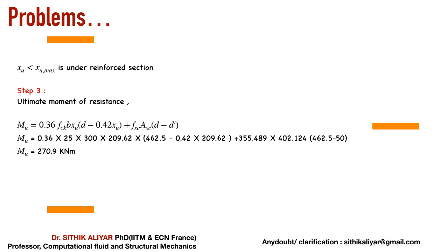I have tried to give you some inputs and I will give you more inputs throughout the classes, such as what the average slab dimensions can be, what the footing dimensions can be, and everything in future classes. For now, the beam moment I have told you is 100 to 200 average for singly reinforced section, 200 to 250 to 300 average for doubly reinforced section. This can be your answer. And AST approximately, if it is a doubly reinforced section, 2000 to 3000 to 5500 mm square. ASC will be 1 by 4 to 1 by 5. Sometimes it can go to 1 by 3 if the depth is high, because depth will take some bending moment, so the ASC value will come down.